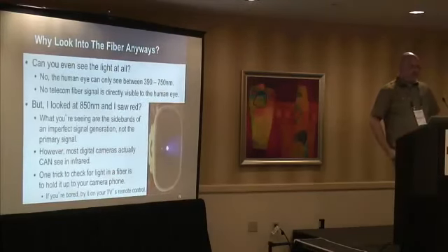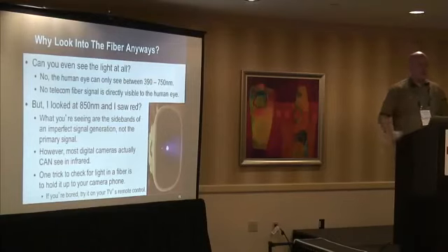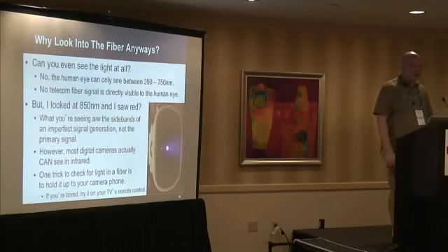So why even look into the fiber at all? You can't actually see the signal, so there's no real benefit to it. When you look at an 850 signal and you see red, what you're actually seeing is a sideband. You're seeing the very edge of red that's out of what you're actually trying to transmit, but the generator is not perfect.